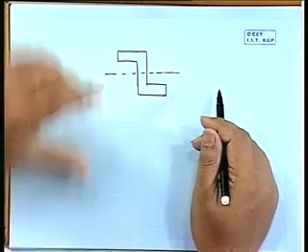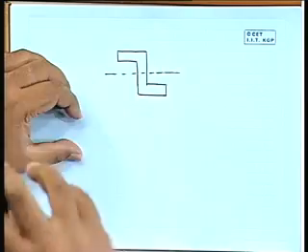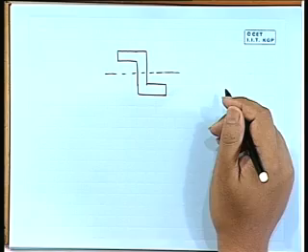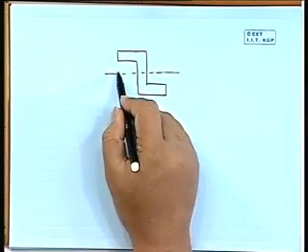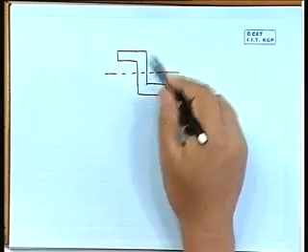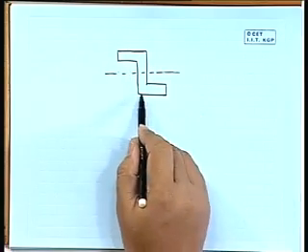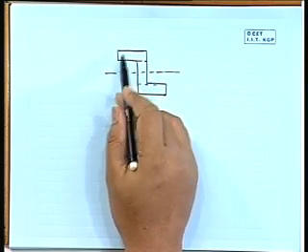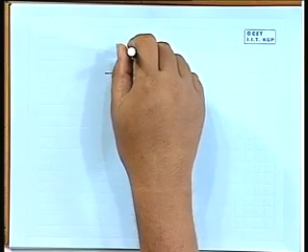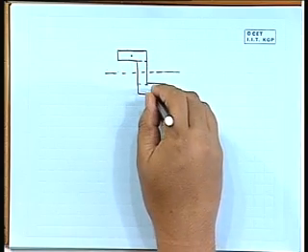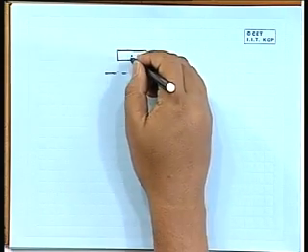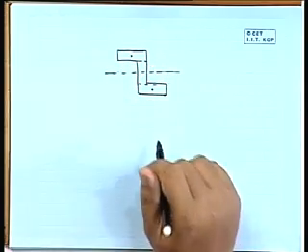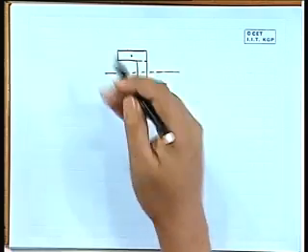Now here what will be happening? Say if we apply a moment, say this is a cross section of a beam and some loading is there, some moment will be there. So your stress will be My by I. So here My and My, it is identical. So stress at this level will be equal to stress at this level. So on this block there will be a resultant force and there will be a resultant force, right. Now they will be equal and opposite. So if it is a moment like this, it will be compressive, it will be tensile, and they will be equal and opposite.